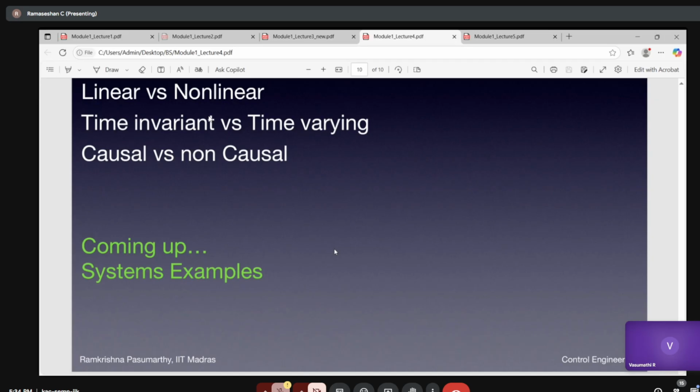Sir, but the reference point is also changing in feedback, because you are measuring the output and giving it back to the controller, right? See, the measured output always changes with time. I'm talking about the reference signal, the reference output. What actually happens always changes with time. But what you want, whether it is constant or varying with time, that's what you should ask. Of course, the speed will change with time, that's what happens in a mechanical system. But what speed do you want? Is it a single number? Correct. Okay, got it.